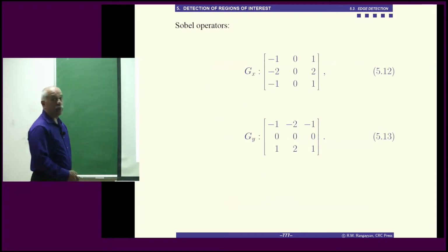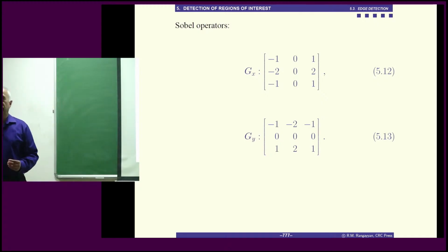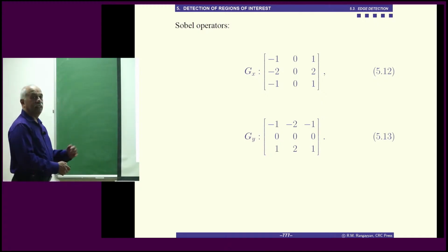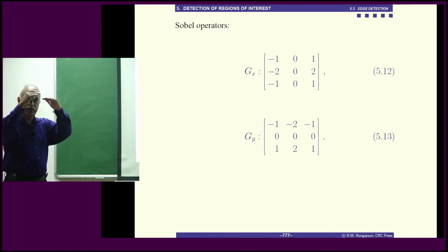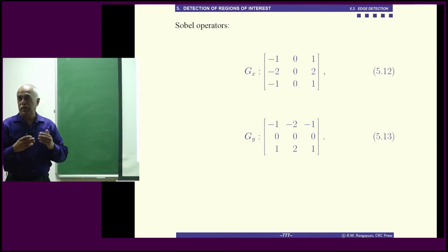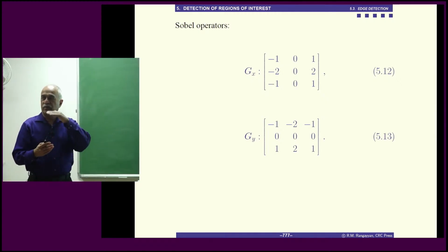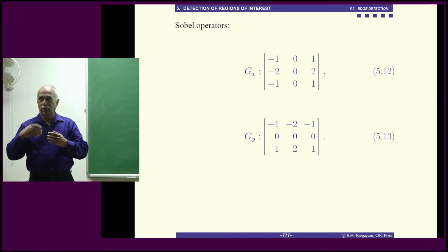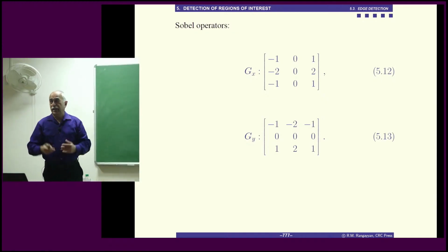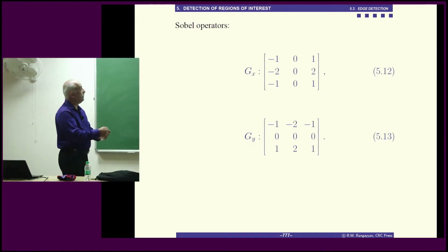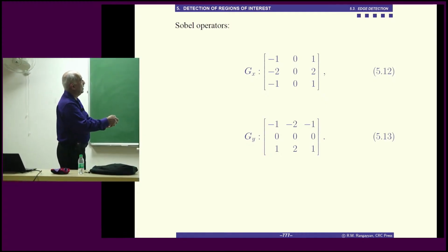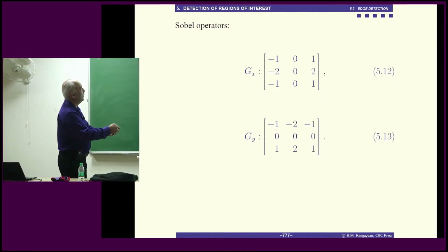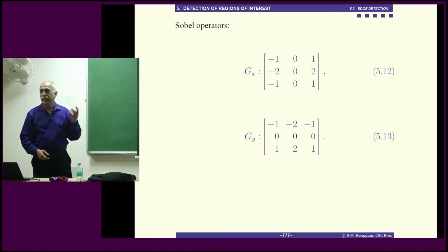Sobel came up with a different idea. Said, well, in the Prewitt masks, those three operators are given the same weight for the current one and the one above and one below. Why not take a weighted average? Give more weight to the current horizontal line, -2, that is, it was -1, double it, and let the others get only half that weight.